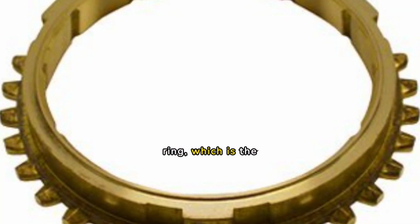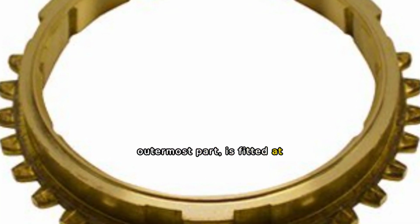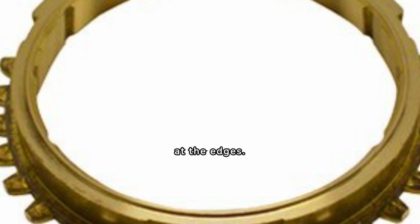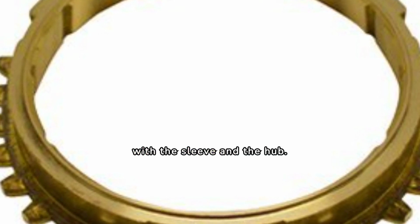Synchronizer blocker ring, which is the outermost part, is fitted at both ends in the synchronizer system. It has straight teeth at the edges. It rotates along with the sleeve and the hub.